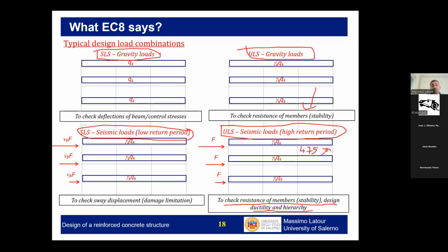So, controlling that the lateral displacement of the building, so the drift of the building, is limited. So basically this is an indirect control on the damage. There are a number of elements in a building which are sensitive to lateral displacement: the claddings, the partition walls, the furnitures, machinery, whatever it is inside. This damage will be controlled, reducing the possibility to have large sway displacement. So the displacement has to be limited within certain boundaries that were listed before by José in the previous presentation.